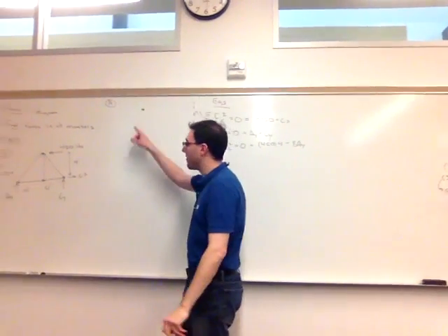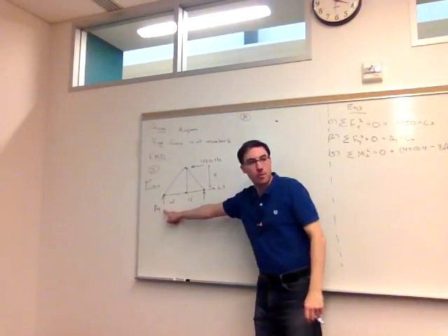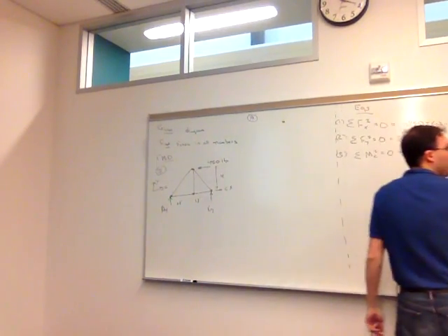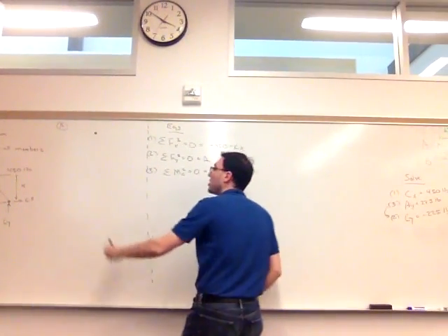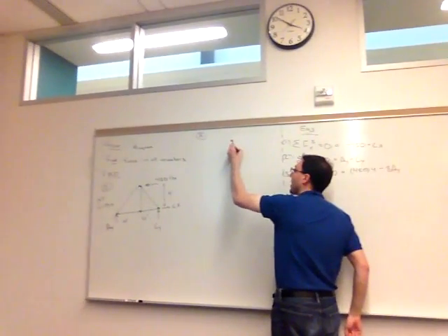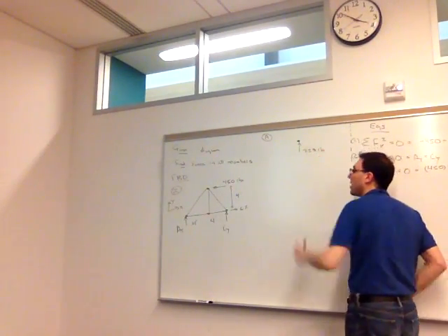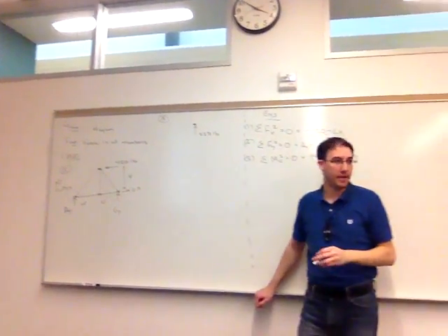Right, so AY affects the pin. We said it was up in the first picture. It turned out that it was positive. So we're just going to copy that exactly. So 225 pounds up. That's from the roller acting on the pin.